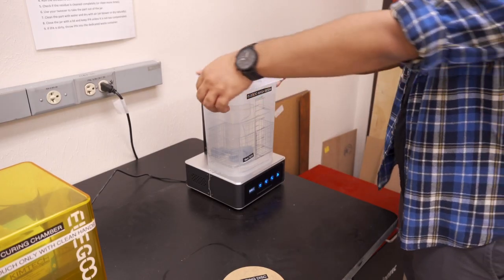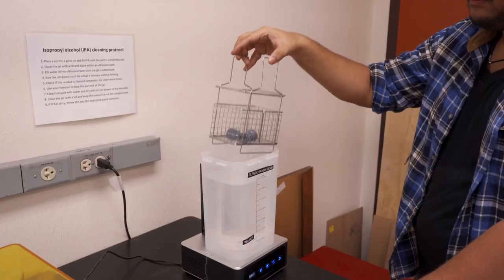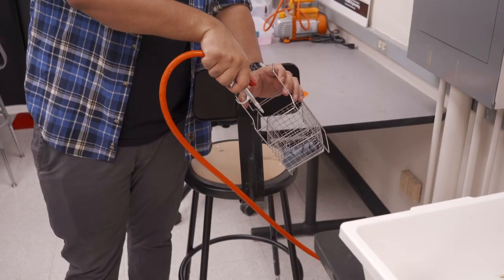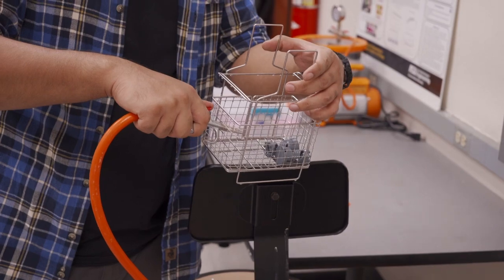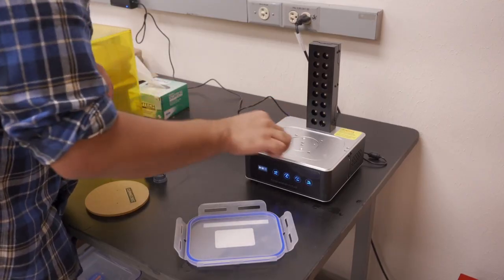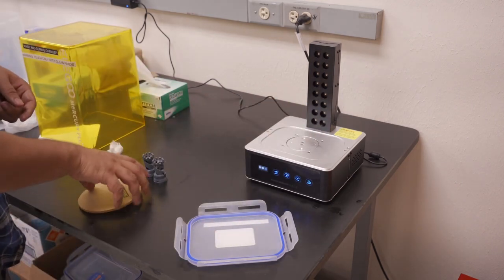Once the washing is complete, next step is removing the moisture before curing. Use a compressor to blow off the moisture. Take caution with delicate parts as the pressurized air could easily damage the print. Wipe off droplets on and around the machine as well.